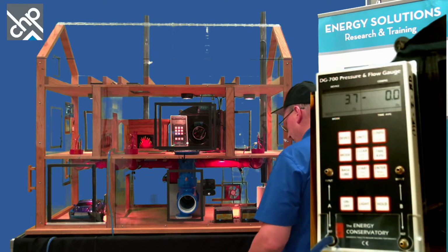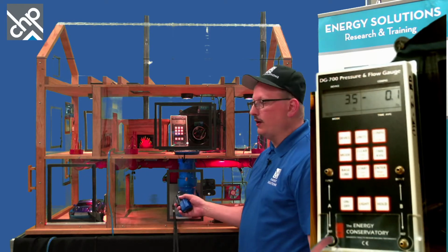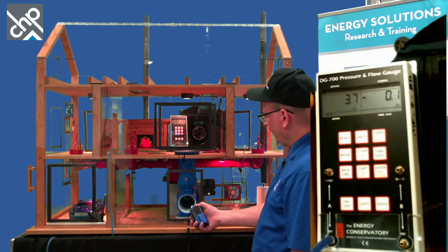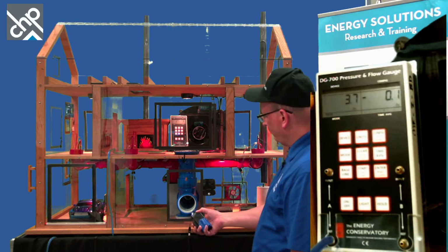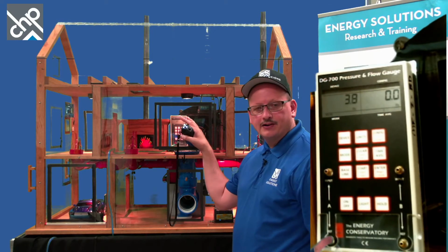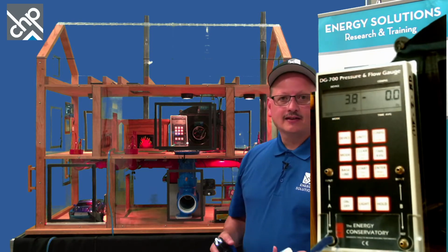Now, down near the leak, down here in the basement area where the leak is, what's going on? If I take my smoke pencil right here, you can see what's happening. It's actually pulling the smoke in. So the main part of the building up here is under a positive pressure, but where the leak is, it's negative. So anything in that space, first of all, if you've got a return in a crawl space or an attic, it's pulling in the air from those spaces, and you're having to heat and cool that.